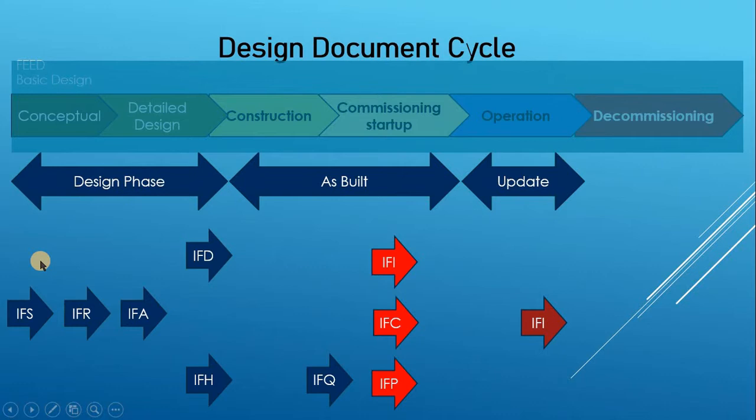However, as we go into each one of those phases, you can find many and multiple issues of the drawing itself. So it could be issued for a squad check, issued for review, for approval, for design, for a HAZOP, issued for inquiries. Then there is a final issue of each drawing, which is, let's say, issued for information, issued for construction, or issued for purchase.